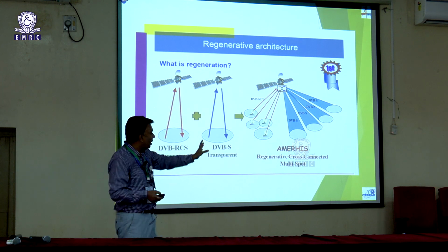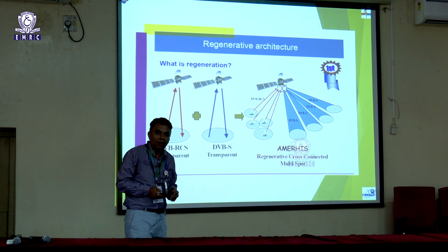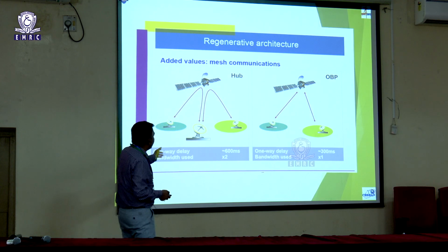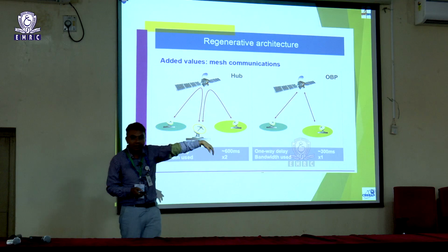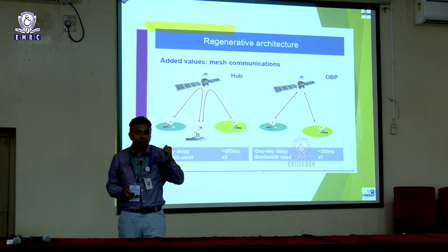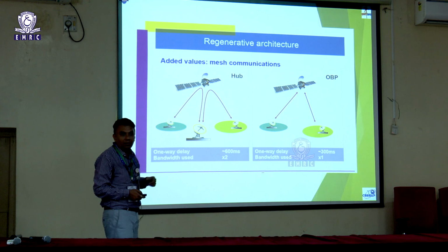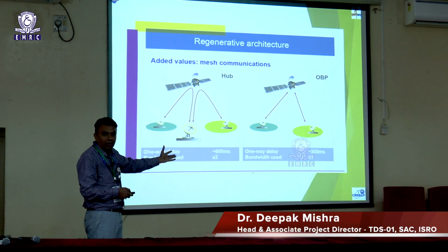That service is already there in Europe, but in India we are now also going ahead with this type of design, called regenerative architecture. In the same way, as we mentioned, initially the user has to send all the data to the hub and then the hub broadcasts. That is called a 2-hop delay. So in order to reduce this hop delay, we are going with onboard processing, where there is no hub sitting inside, and all the data goes directly from terminal to terminal.